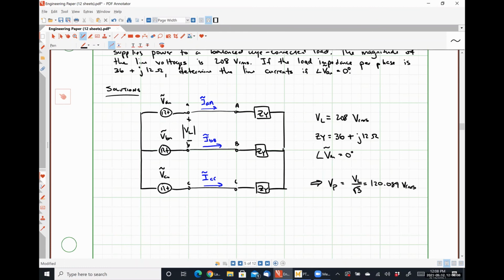The reason why I chose to use 208 is because if you were to open one of the breaker panels here in Methkin Hall, or if you were to, I think my office still has a 3-phase system. My old office definitely did, but you might see something along the lines where on the panel, it will say 208/120Y.